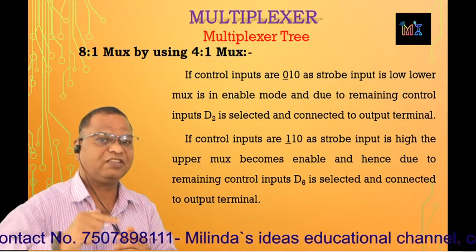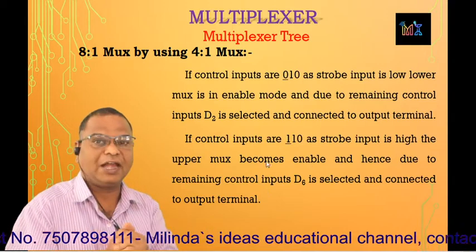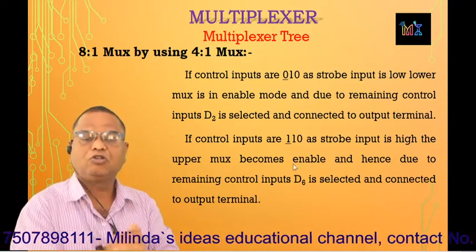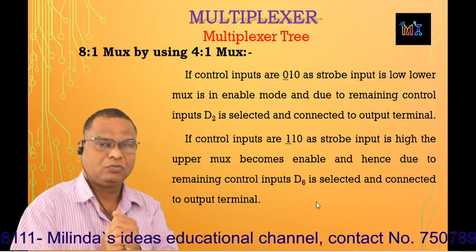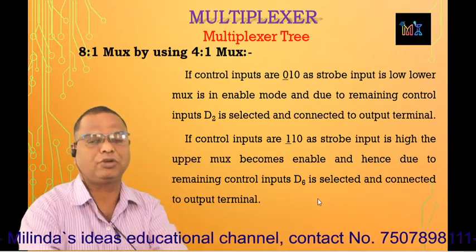But friends, in this case the I2 terminal of the upper mux is selected and fed to the output terminal. So in this case that data, that is D6, is selected. So from D0 to D7, the data D6 is now selected and fed to the output terminal.